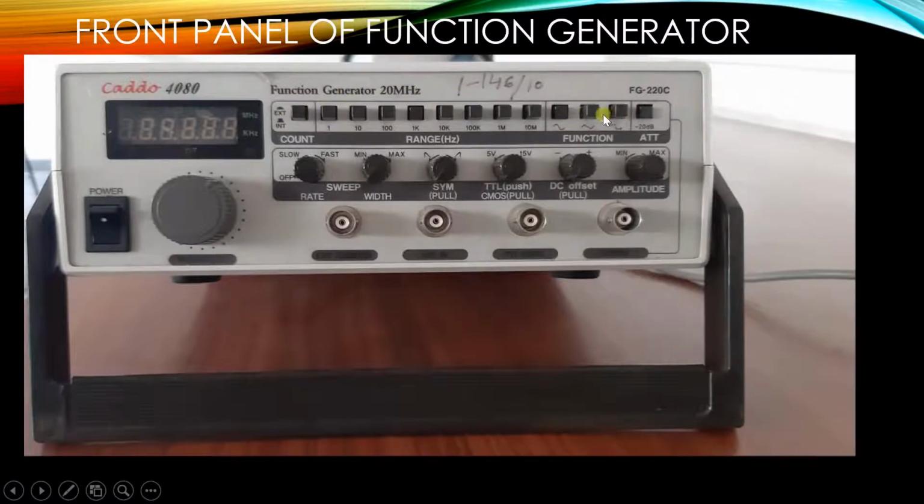And these three buttons are the shapes of waveforms. If we press this button, this gives a sinusoidal waveform. If we use this button, this gives a triangular waveform. And if we use this button, it gives us square waves. And the rotary button is for the calibration. For example, if we want a frequency of 12 Hertz, then we press this 10 button and rotate this button, and here we will get the 12.